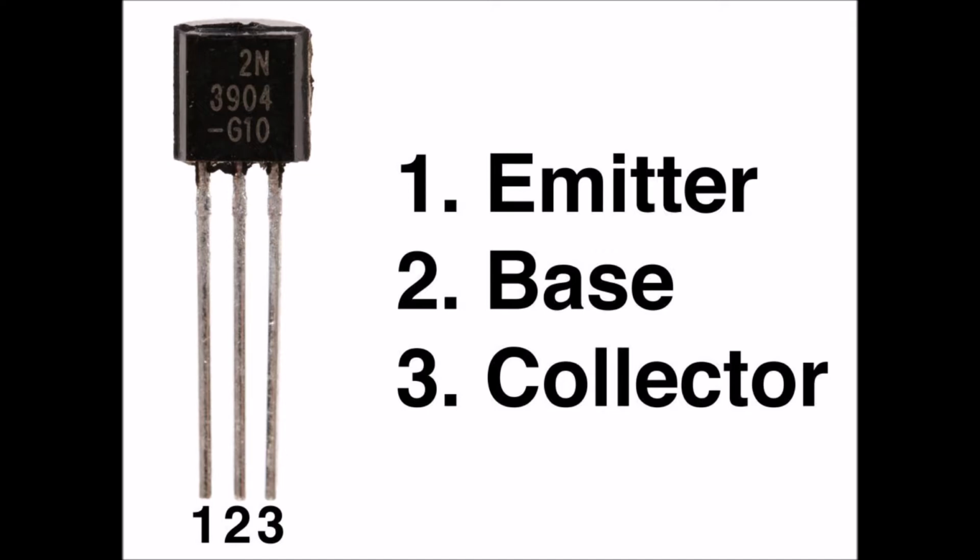A transistor can have considerable gain at its alpha cutoff frequency. By looking at this specification for a particular transistor, we can get an idea of how rapidly it loses its ability to amplify as the frequency goes up.